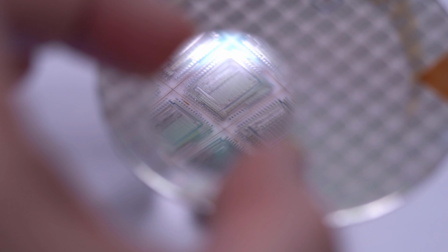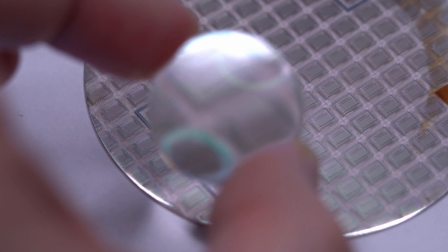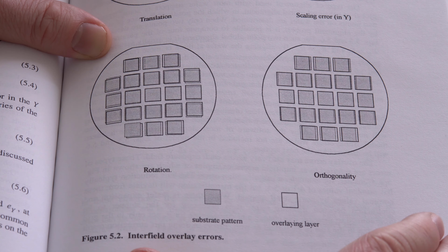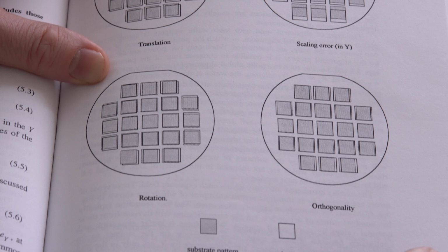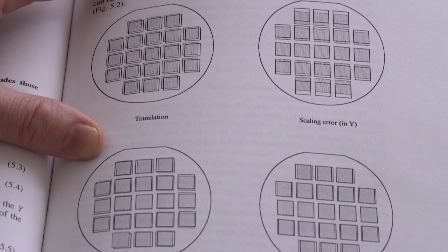There's also a surprisingly large amount of variation in the quality of the final product of silicon chips, even those created in the same batch. There's a multitude of problems that can happen during the lithography process of creating the RAM chip. This can be due to things like optical aberrations in the lens system that was used for the lithography. It could be seismic or environmental vibrations, even vibrations of someone walking nearby, or a very common and very low magnitude earthquake that's so subtle humans can't notice it.